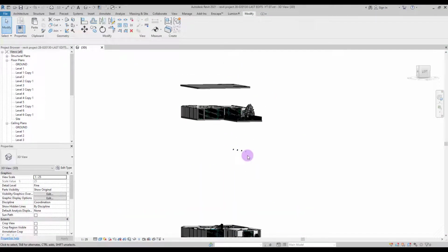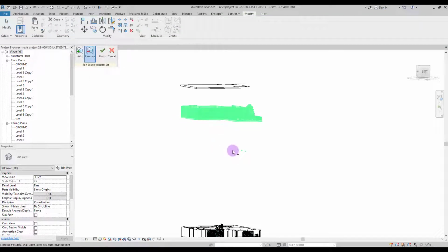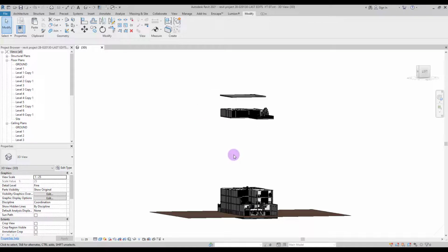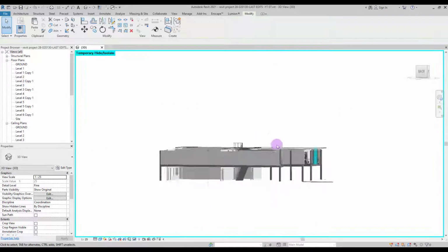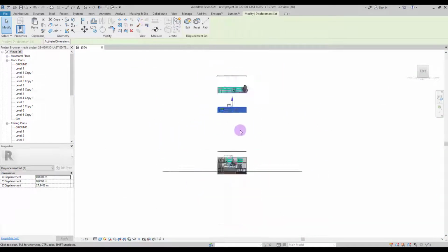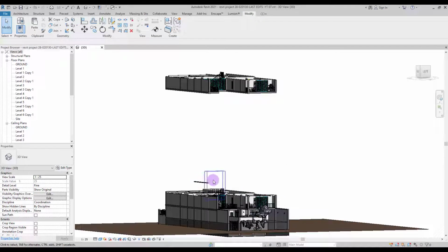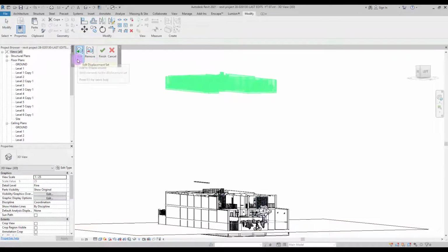As you can see here, we have selected this line accidentally. To remove these, you need to select them and click on Edit, select Remove and select them. Now move the next level. Apparently, we forgot to add this object to this selection. To correct this, select your set and click on Edit. Make sure Add is active and then just select your object.